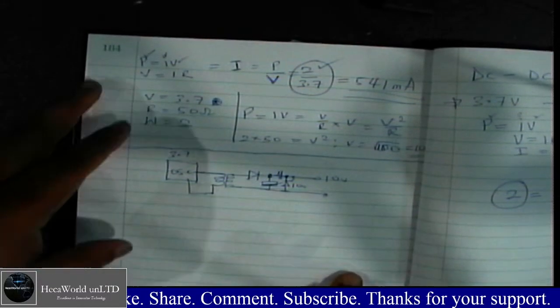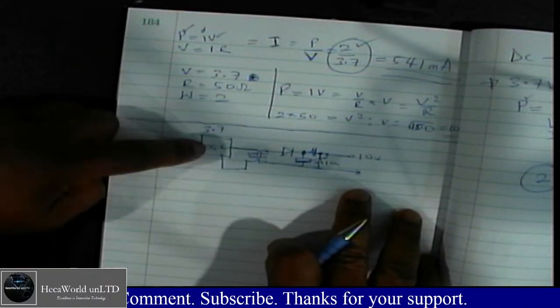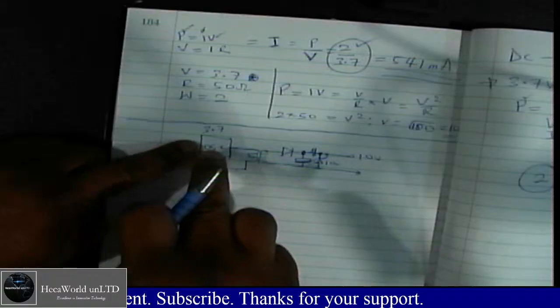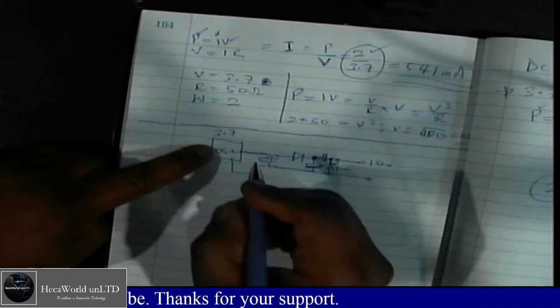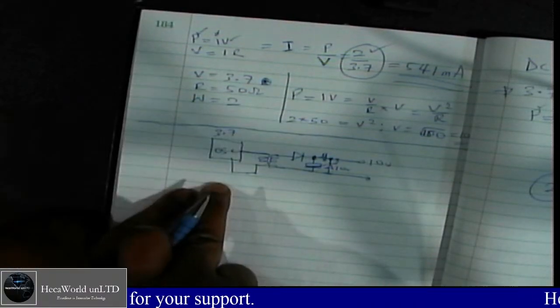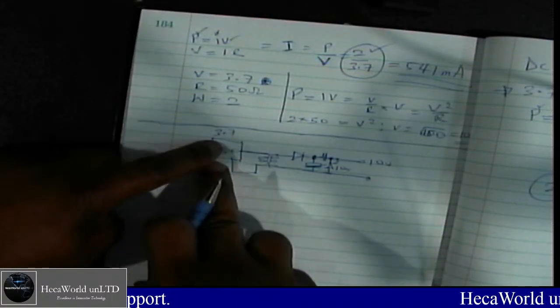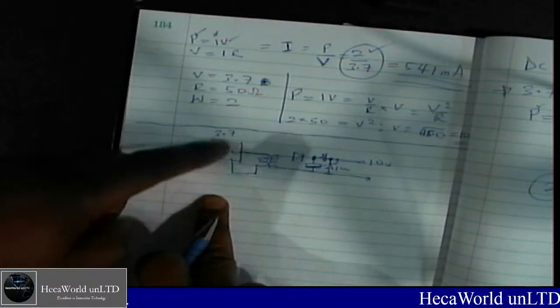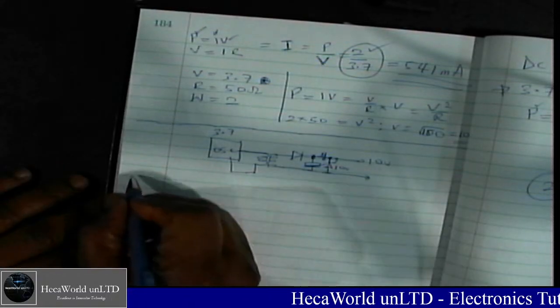Everything I did was kind of acceptable at the time, but that's a longer way to go, because this oscillator will require me to use 2 transistors to generate an astable multivibrator, or to use a 555 timer to generate the frequency, the pulse width modulation, and then I'll have a transformer, and then I have all these other components. So that's how you can do that.